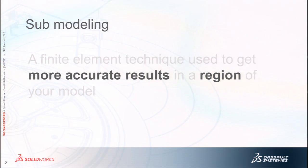So at a high level, submodeling is taking a portion of your model. You did the analysis on the structure. It could be small or big. It's a multi-component structure. And then you identified critical regions, and you want to get more granularity of results in that region. Submodeling will help you do that without having to run the whole bigger assembly again just to get more granularity on certain regions. So we're going to use submodeling to do that.